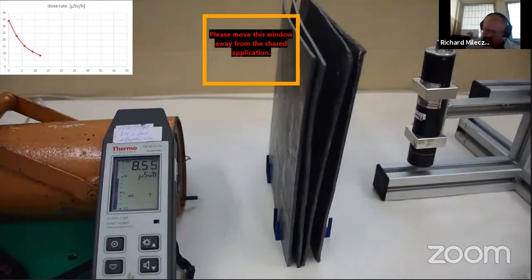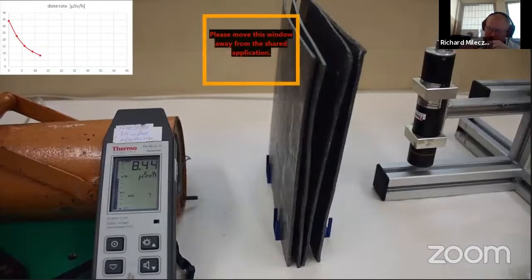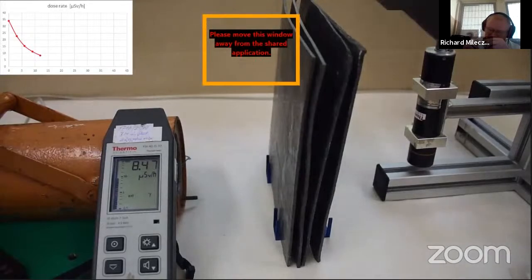But when there is a sudden change in dose rate, for example, this moving average takes some time to reach the actual value. And even when it's at the actual value, you never see the same value, or well, you can see the same value, but the chance of measuring the same thing twice is very low. So because of its probabilistic nature, and because we are using a moving average, the detector slowly gets to the point where it can, and then it has peaks and valleys.